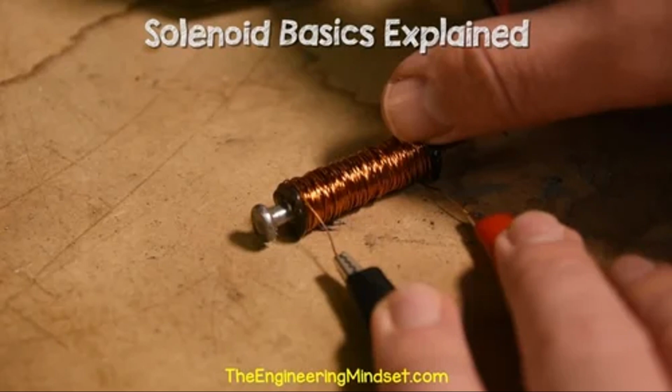The principle of operation of solenoids relies on the generation of a magnetic field by an electric current passing through a coil, which interacts with a movable core to produce linear or rotary motion. This basic principle is applied in various devices and systems where controlled mechanical motion is required. Linear solenoids. Linear solenoids convert electrical energy into linear motion. They typically have a plunger or rod that moves in or out of the coil when the solenoid is energized. Linear solenoids are commonly used in applications such as door locks, solenoid valves, actuators, and automatic door openers.